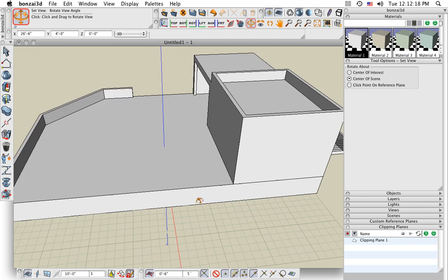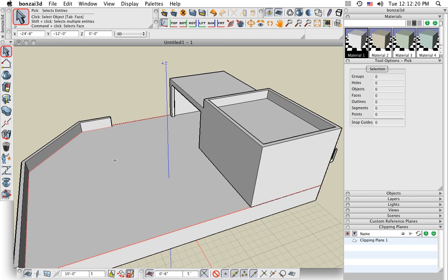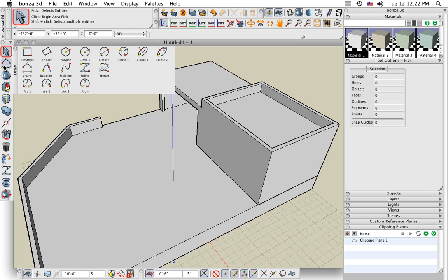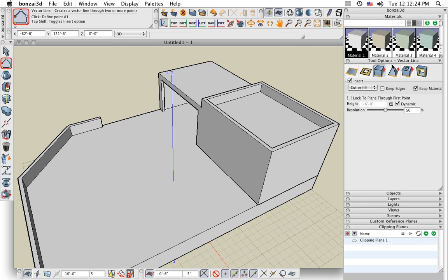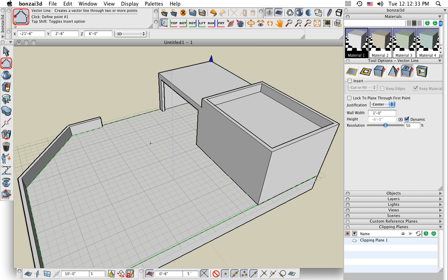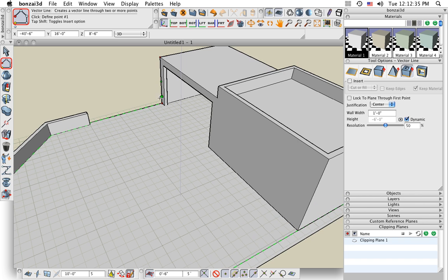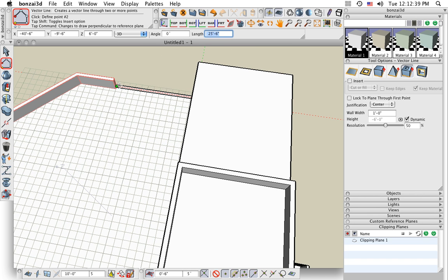Okay, let's add a few more elements in here. Back to my basic drawing. So you've seen how to draw straight extrusions. We can also draw 3D walls directly. This happens in the same fashion, so I adjust my reference plane and snap to points and start drawing. So I'm starting to draw that wall, snap to the endpoint of the wall here.